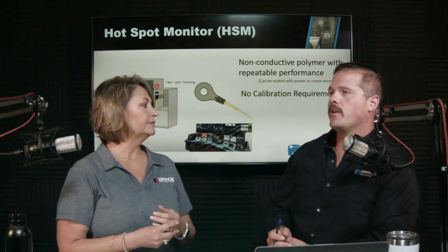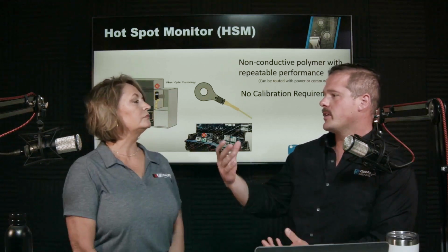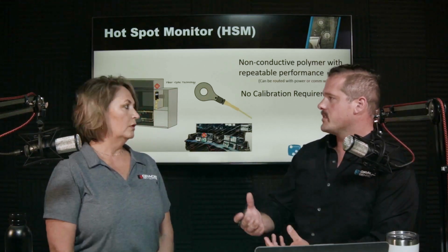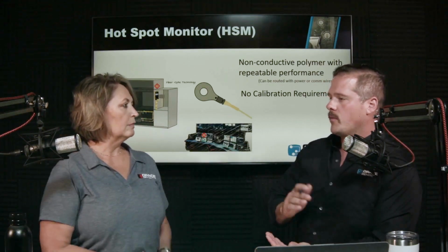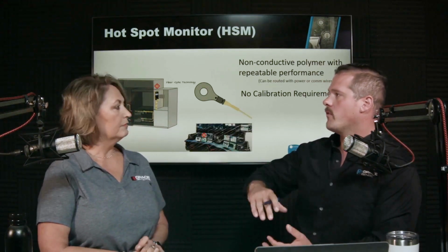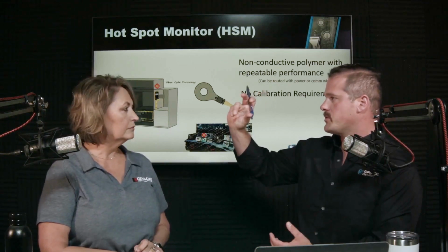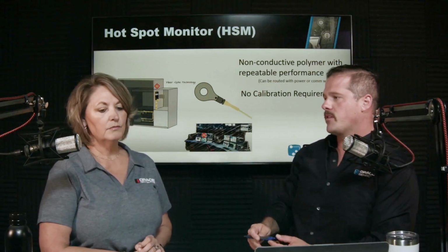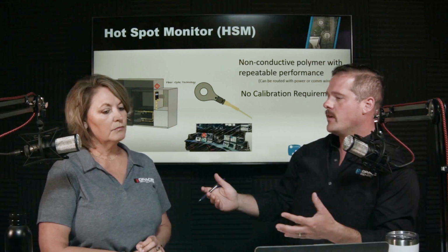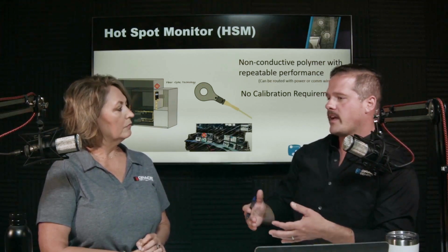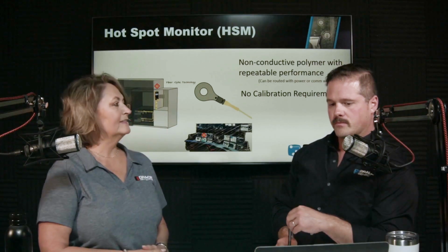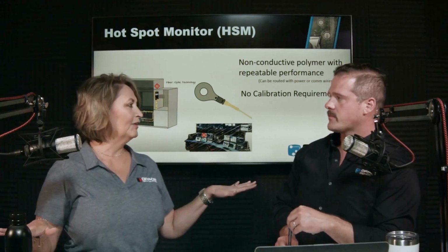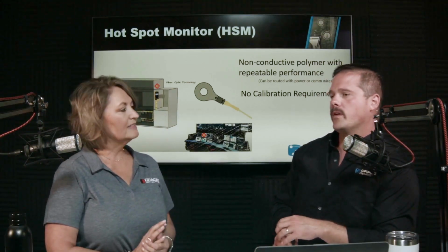thermography scans. And we know what a rated temperature is on a piece of insulation that's going around a bus, right? So we're really trying to make sure that even in hot months, we're never going over that kind of insulation temperature rating and various other things. And so expanding out our interval. I mean, the ROI on expanding out that interval must be substantial. I'm sure it is in every industry across the board. Yeah, I'm sure it is.